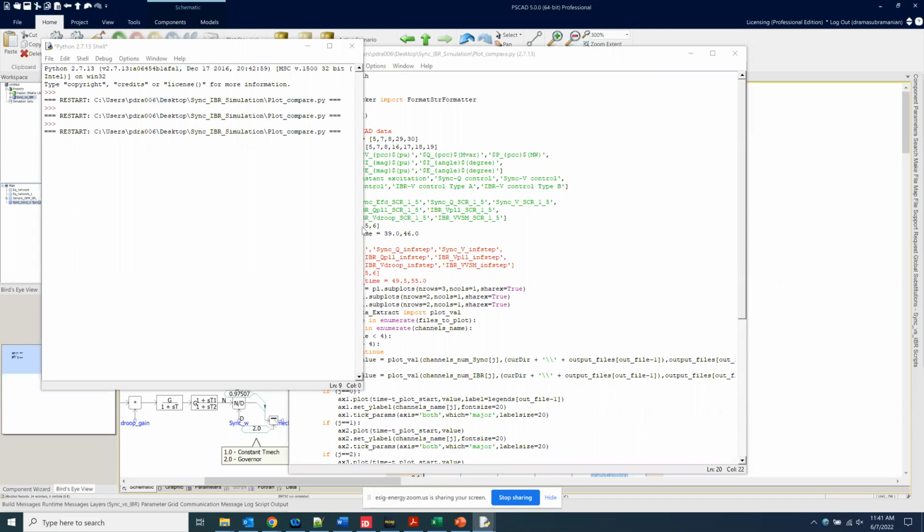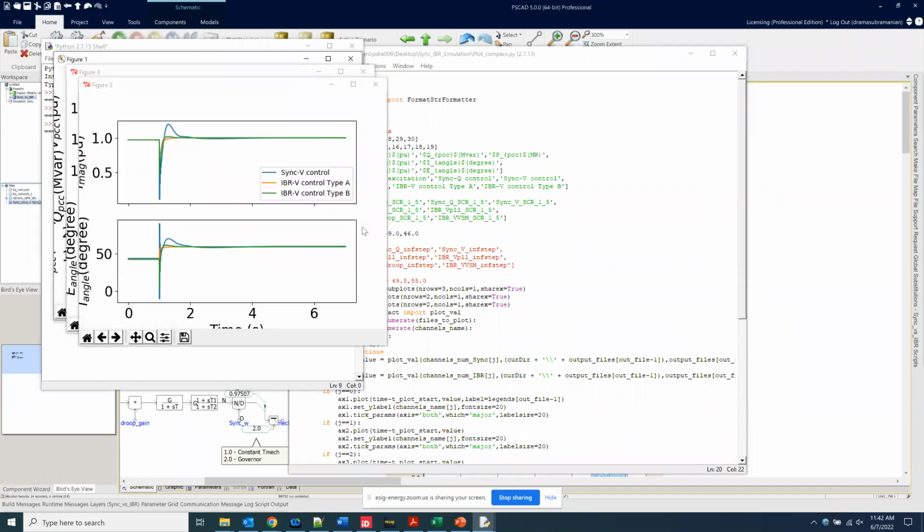without only specifying voltage behind impedance, but rather specifying the performance or the service that you want from the inverter. So if you specify just voltage behind impedance, as we saw in the synchronous machine case, if it's just a voltage source behind an impedance, but you try to change that in a way where you're controlling Q, you can still become unstable. So just specifying voltage source behind impedance is not a sufficient condition for grid forming. What you might need is to go down to specifying fast voltage control at the inverter level instead of having fast Q control.